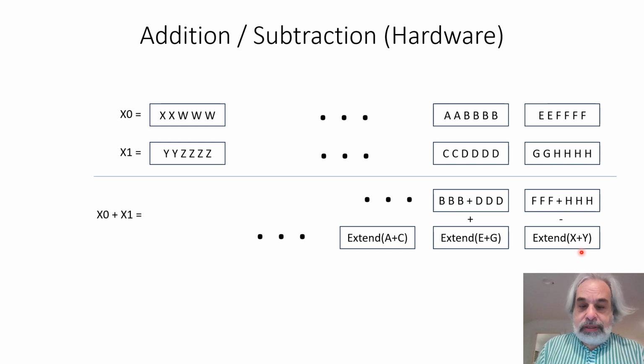And in this way, you could support a 32-point NTT entirely in this format, without ever leaving this format. And that, I think, would be extremely efficient to do in something like an FPGA. Okay, I think that's about it for the hardware portion. I guess I showed an addition here. A subtraction would just obviously be all of these pluses turn to minuses and all these minuses turn to pluses.